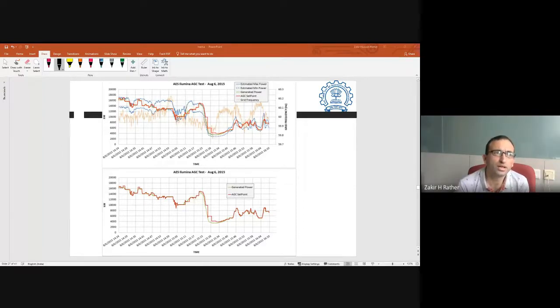See, for a wind turbine generator to provide inertial support, you do not necessarily need to operate it at a deloaded point. You can operate it at the MPP point, and since you have the rotational mass there, you have already stored kinetic energy. You are releasing the additional power from that stored kinetic energy. So you don't need to operate the wind turbine generator at non-MPP if you are participating in inertial support, because you are providing the additional power from the rotational mass of the machine. But if it is a solar PV system alone without storage, then if you are planning to participate in the inertial support, you have to operate it at a suboptimal point. You need to have a margin for that.